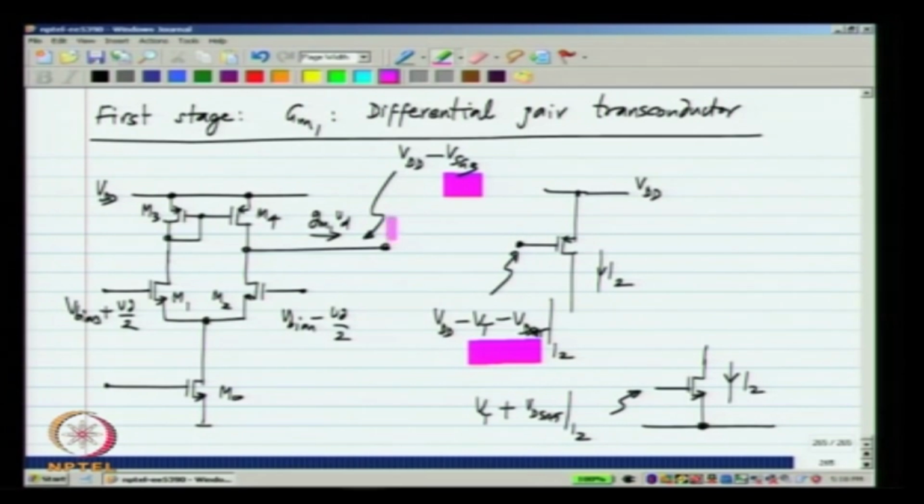So, it is a lot easier to interface a PMOS stage to an NMOS differential pair compared to an NMOS second stage. For this reason we will use a PMOS second stage with an NMOS first stage, that is, an NMOS differential pair first stage. Now, the other topology is also possible. You can use an NMOS second stage with an NMOS differential pair, and that is sometimes used when the supply voltage is very low and you can satisfy these constraints, but usually an NMOS differential pair will be followed by a PMOS common source amplifier. I say common source amplifier, but what it really is, is a voltage controlled current source that we will use as an amplifier.